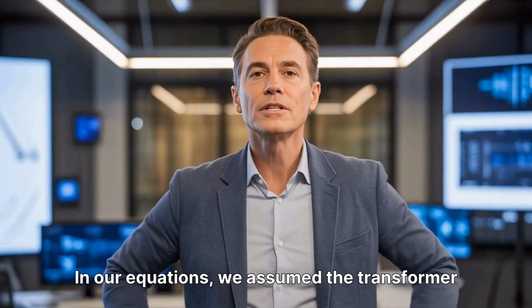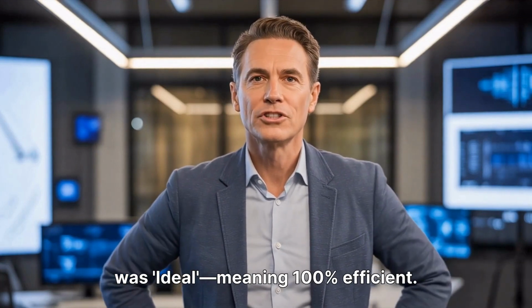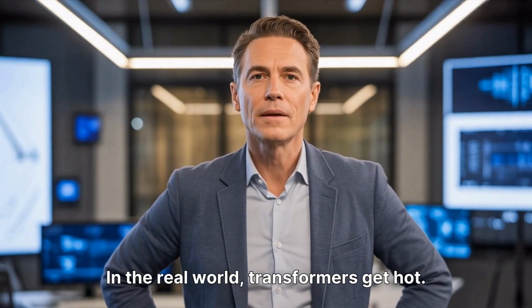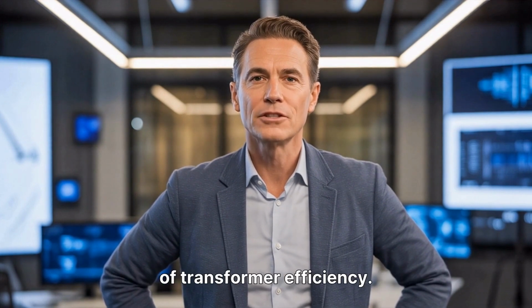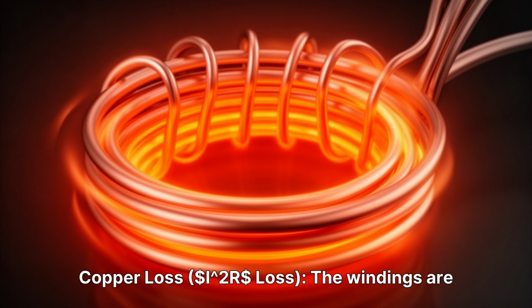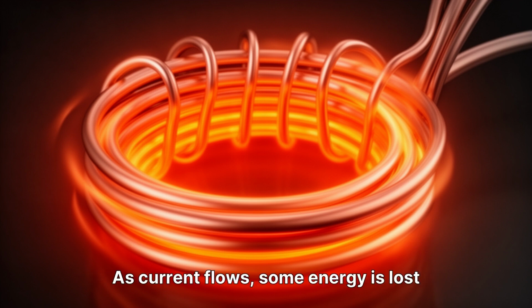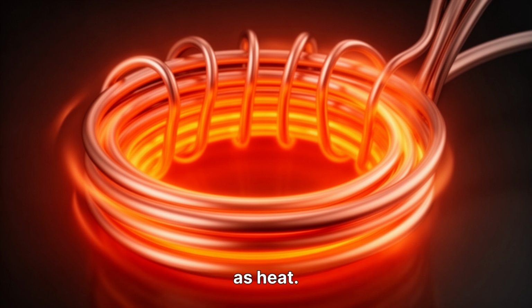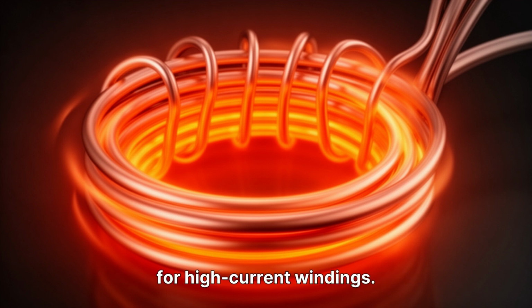In our equations, we assumed the transformer was ideal, meaning 100% efficient. In the real world, transformers get hot. That heat represents wasted energy. Let's look at the four main enemies of transformer efficiency. 1. Copper loss, I squared R loss. The windings are made of copper, which has some electrical resistance. As current flows, some energy is lost as heat. We minimize this by using thick wires for high current windings.